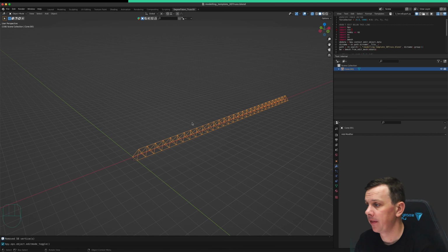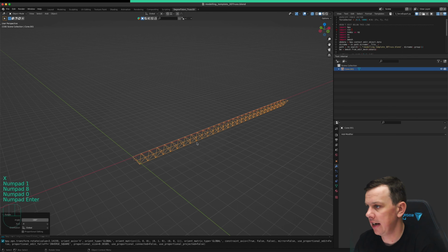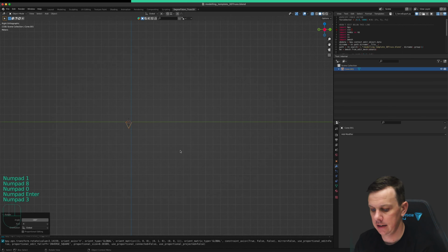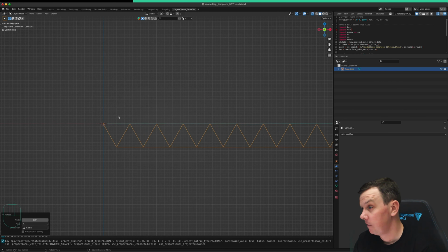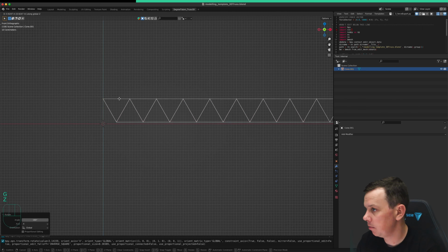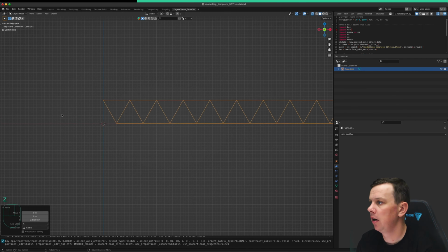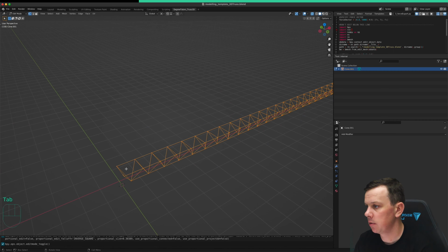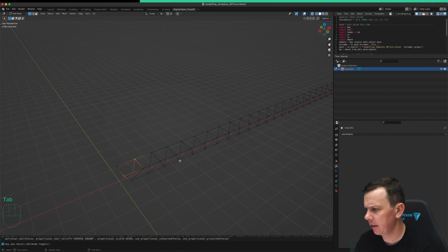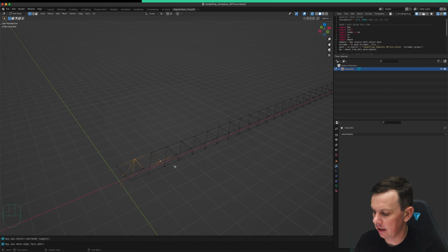We're nearly there. Now what I want to do is rotate this thing about the x-axis by 180 degrees because I just want to invert it. Let's go into side view mode. That's going to currently be below the ground plane, and so I want to G Z move that up. We can just eyeball it for now, it doesn't really matter. So now I just want my out of plane bracing in this thing. So I'll tab into edit mode and I'll fill that guy,